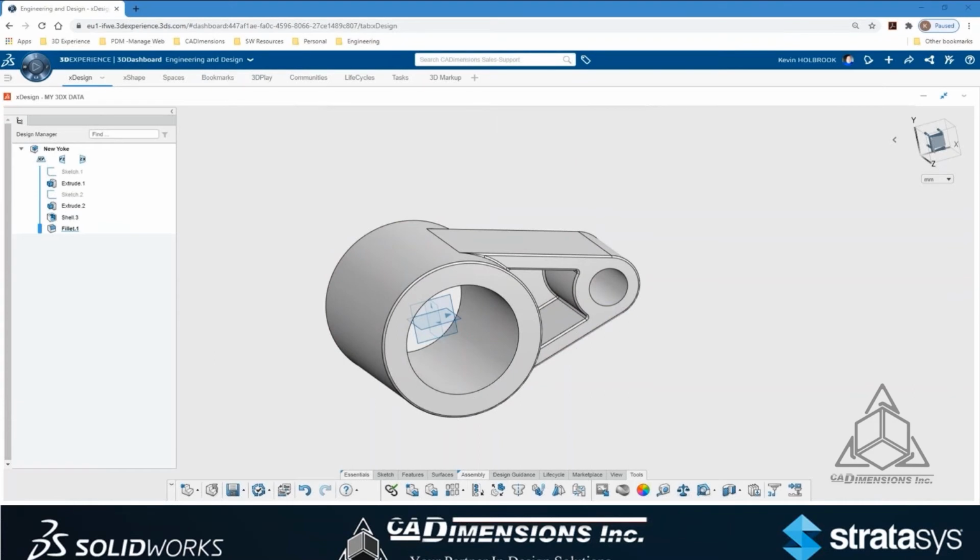And look over in the design manager, in SolidWorks known as the feature tree. You can see very similar structure, history based, all your sketches are in there. That little slider bar to the left is the rollback. If you drag that thing up, it'll roll back in the tree. So some very nice functions, but things that we're really used to, Tom.